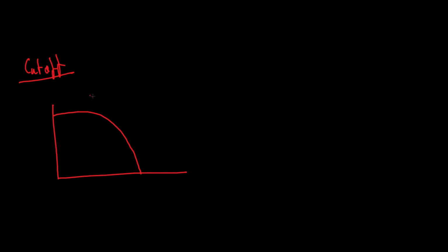Okay, next look at the cutoff frequency. You probably already know cutoff by now, but let's look at it again. So when you have a filter, this is a low pass filter as an example, you have this point, cutoff. But what exactly is a cutoff frequency? Well, the cutoff frequency is 0.707 of the max amplitude.